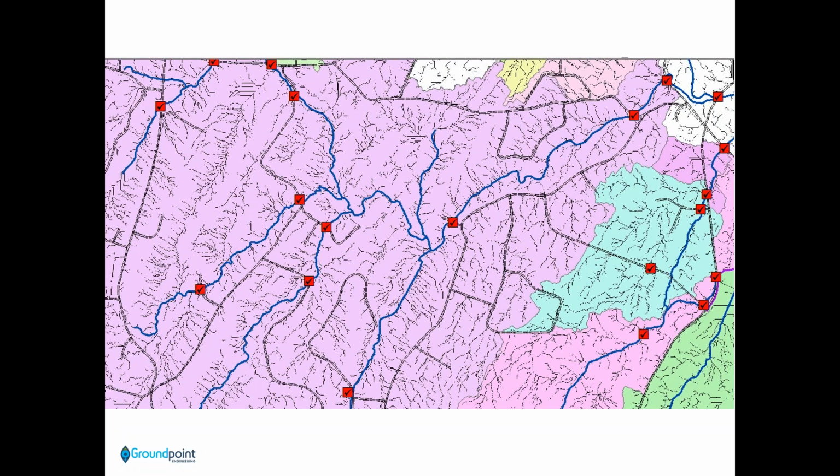So if you want to evaluate the town culverts, that would require some additional cleanup and assessment of the catchment areas to each of these. But if you only want county culverts, you don't have to worry about the details inside the catchments, just the boundaries. So it's a scalable process. You edit the data and clean up the surface model at the scale that you want to analyze. You don't have to look at every single pixel.